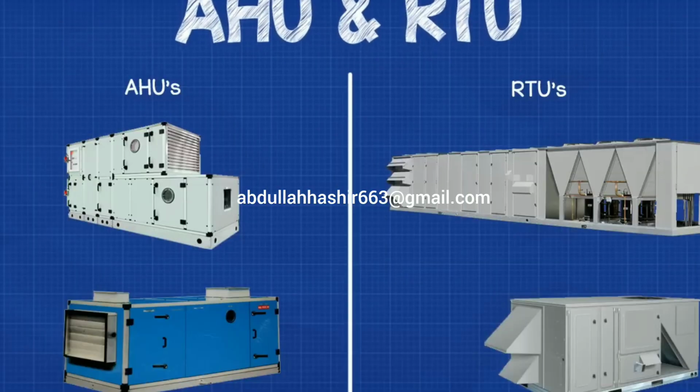AHUs and RTUs, air handling units and rooftop units. Now these two systems both serve a very similar purpose, and they can even look fairly alike. Both of these are used to distribute air around the building and will contain fans to achieve this. They will both take in fresh ambient air and clean this through a filter before heating or cooling the air to suit the demands within the building.